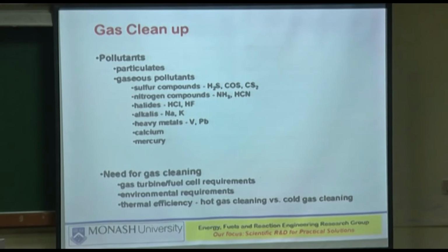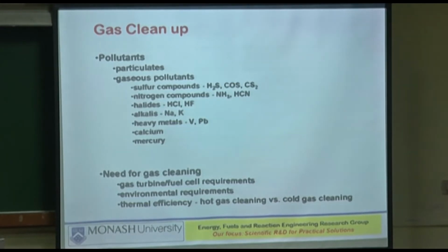So cold gas cleanup definition is easy. You're cooling everything down so as to take all the alkalis out, all the condensable species out, particularly the alkali and the moistures are all gone.